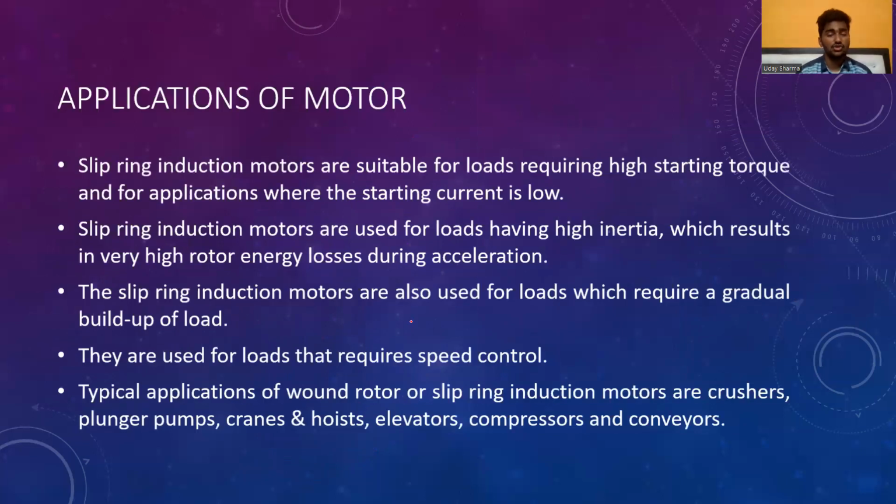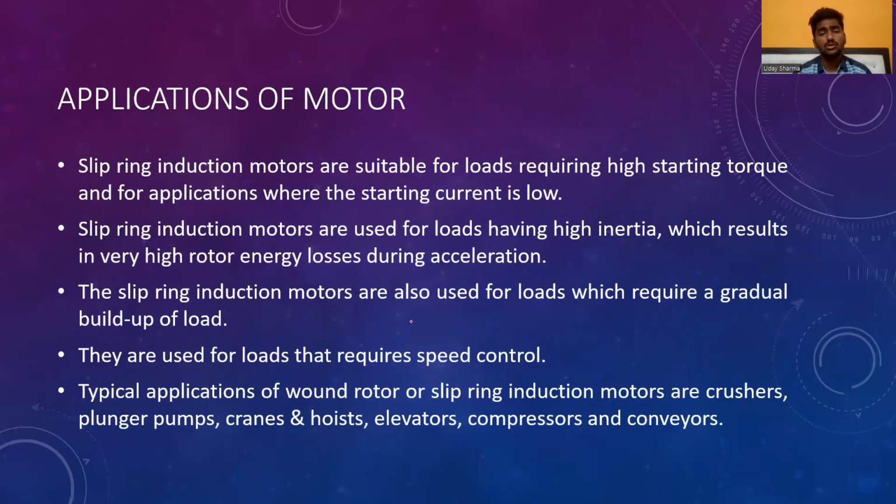Let us discuss the applications of motor. Slip ring induction motors are always suitable for loads requiring high starting torque and for applications where the starting current is low. Like if you need high starting torque in any conditions, we can use a three-phase slip ring induction motor.